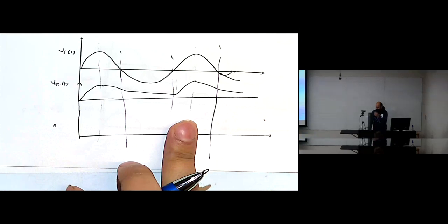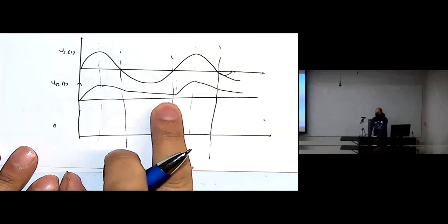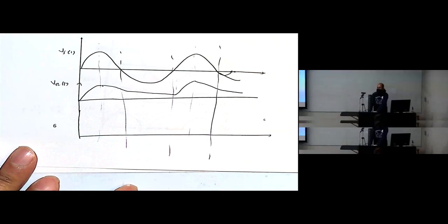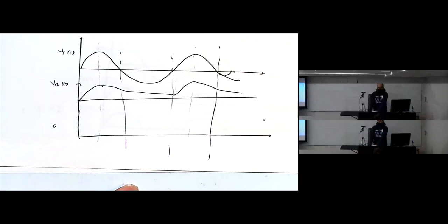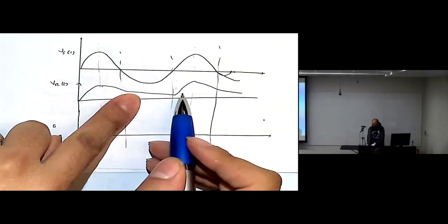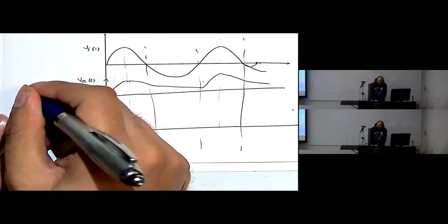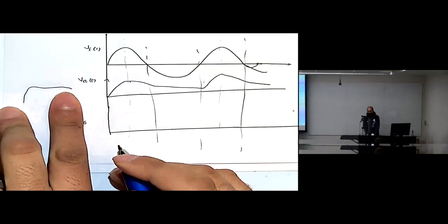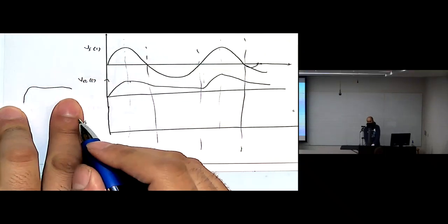So in this waveform, we see it will not touch zero. So it will still have some positive value. And if the capacitor is big enough, we will not see that large slope. If the capacitor is a very large value, then it will be very smooth, or with lower slope.